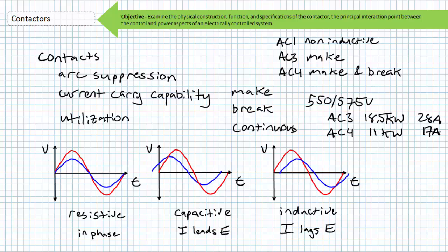A solid state contactor is also a means of establishing and interrupting current to an electrical load. However, it does so via non-mechanical means. The principal disadvantage of contactors is that they are composed of moving parts that can wear out. Additionally, a contactor, being made of moving parts, can only switch so fast before contact bounce becomes an issue. Enter the solid state contactor. This is a device with no moving parts that can not only switch on or off an electrical load at speeds much greater than an electromechanical contactor, thereby influencing a driven load's operating characteristics, but also do so at key times.